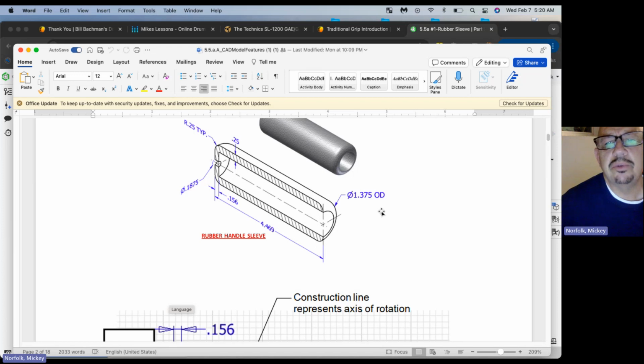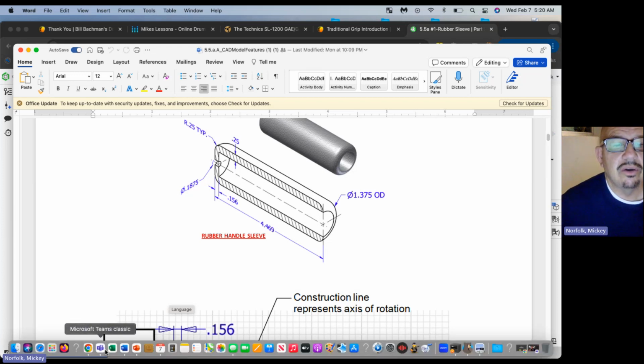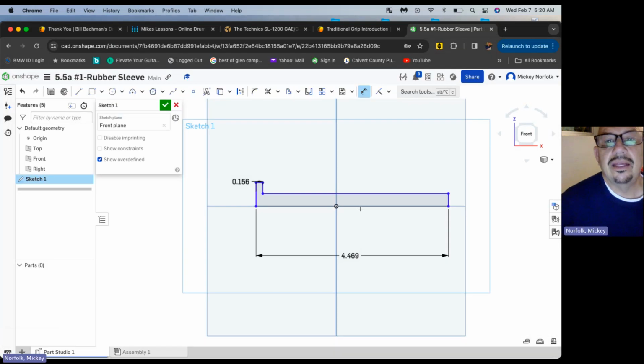I don't know if that helps me with the thickness of it. That is also the diameter, which is 0.1875. And then it's got this, which is referring to the fillet at 0.25. We've already done 0.156 in that. So look at this. This is just showing you the top part. If we revolve this, which it wants us to do, the thickness is 0.25. So let's go back and let's dimension from that line to that line, 0.25.